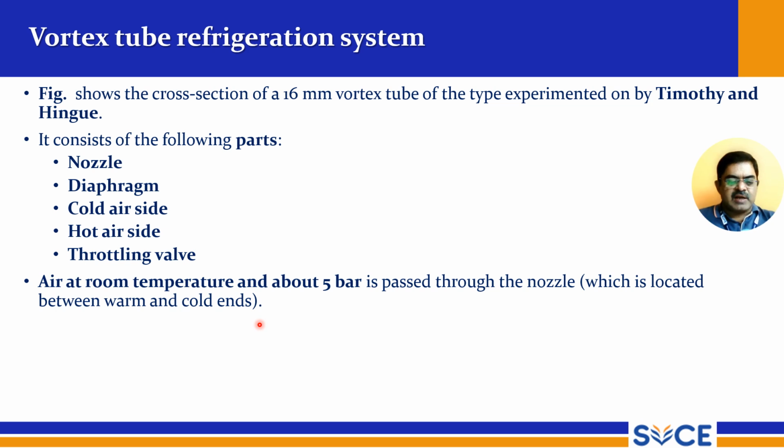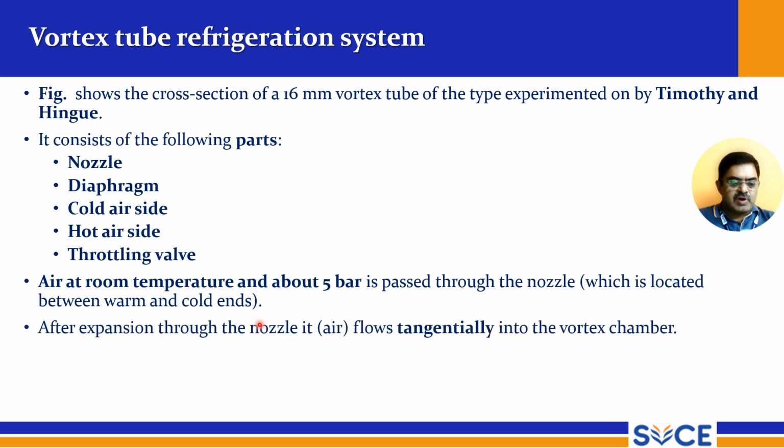Here the nozzle and diaphragm are both kept between the cold and hot sides. After expansion through the nozzle, the air enters tangentially into the vortex chamber.